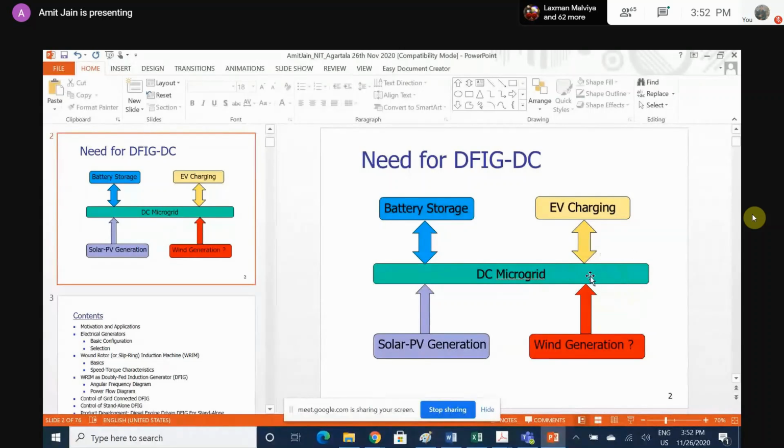So if there is a higher load, you have to support it. The load has to be supported by this. Maybe there will be help from other sources, but the job is more difficult. So a voltage controller has to be in the picture. But in a grid connected system, there will be no voltage controller, no VDC controller, because somebody else will be doing that job.